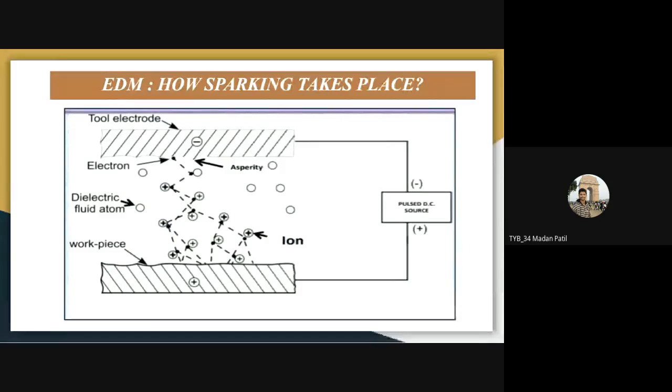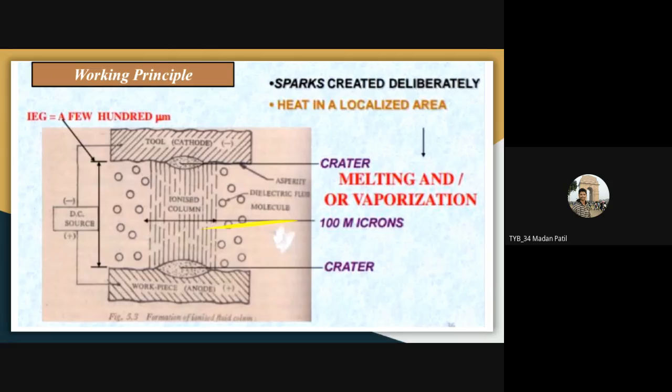If you change the polarity, then tool wear will be maximum. And if the tool wear is maximum, then you will not get the perfect replica of the tool in the workpiece. So we have to keep that in our mind.